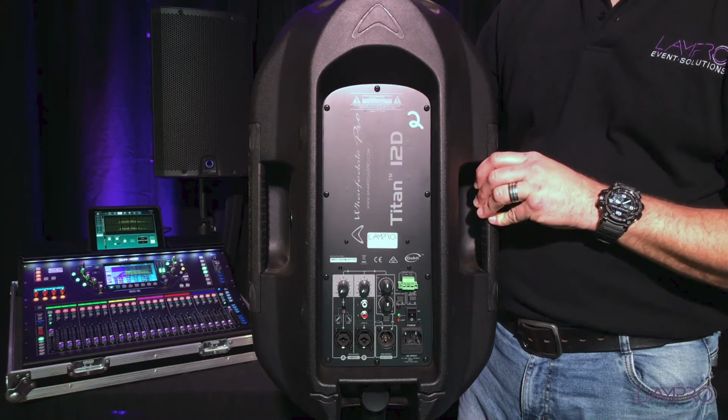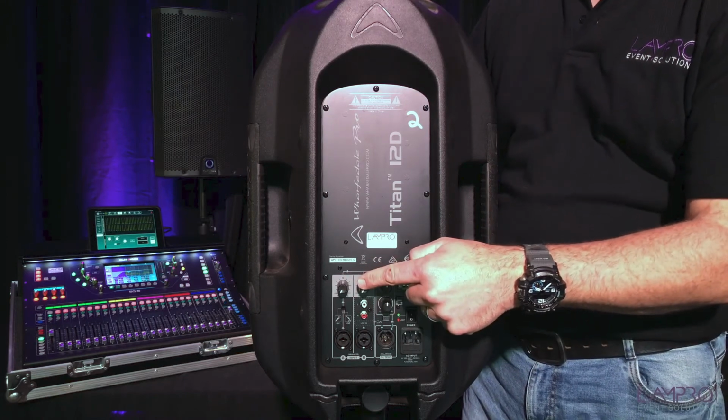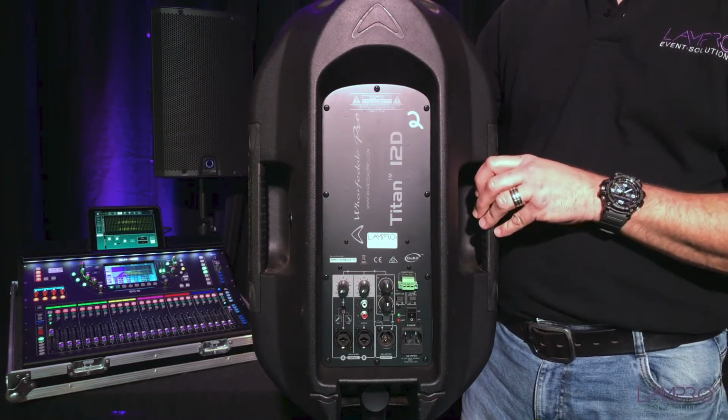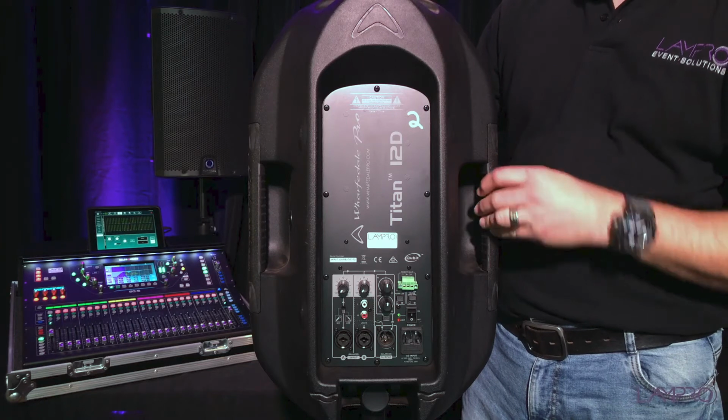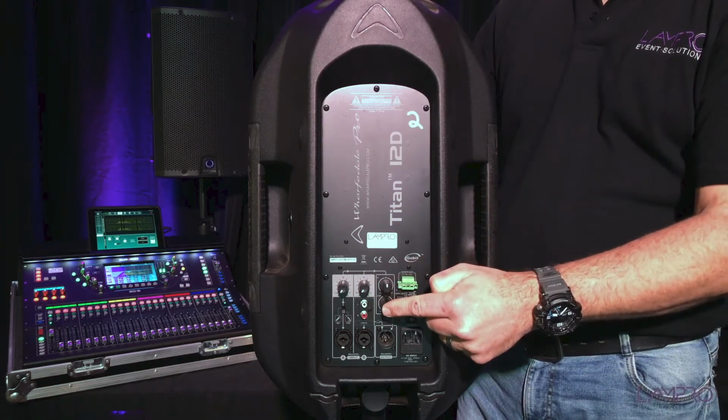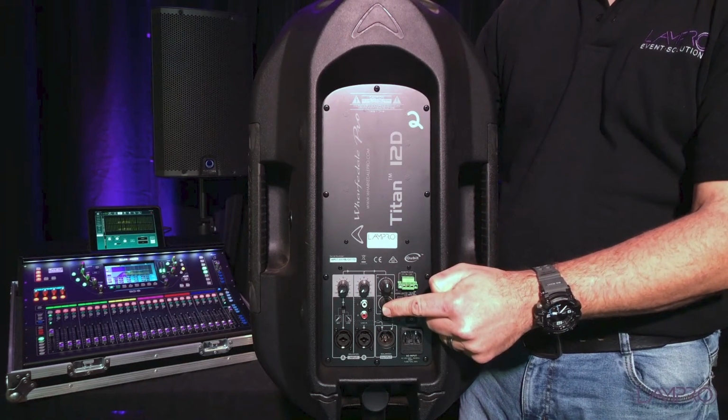Each channel has its own level adjustment that can adjust the overall incoming level into each channel, and the high and low parametric EQ will adjust the high and low frequencies of the speaker. So let's have a look at loudspeaker application and placement. This is a topic that will also be discussed in our next session that will deal with front of house and monitor mixing for live sound reinforcement.